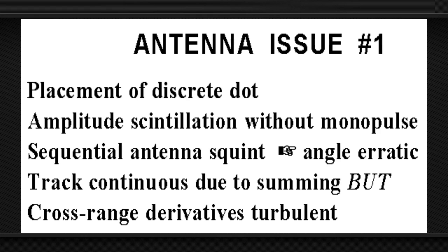From experience, I know that track continuity isn't a problem, and there's a simple reason why. By characterizing target dynamics over a few seconds, with that previously mentioned couple dozen hertz update rate, the tracking algorithm is effectively averaging a big collection of those zigzag indications. Position error is thereby reduced by an order of magnitude. So the antenna can keep putting the target inside the beam. Also, because a long-range measurement accuracy is adequate, Doppler as well as range gate placement is dependable.